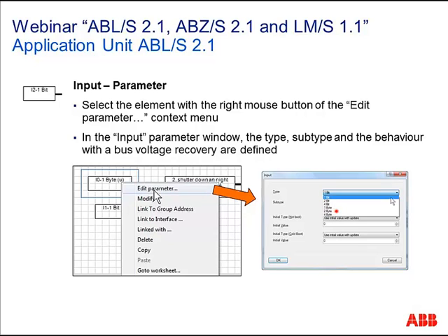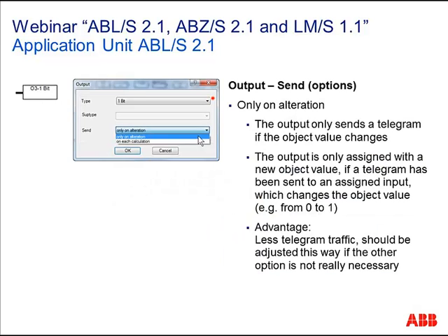When you select, for example, a 2-byte size, you can additionally select the value in the subtype. It is signed, it is unsigned, or it's a float value, for example. On our output, we also have some parameters. Right-click on our output element, Parameters, and then we can also select the size, the type of our output: the same 1-bit, 2-bit, 4-bit, 1-byte, 2-byte, or 4-byte value. And again the subtype, if it's a 1-byte, 2-byte, or 4-byte.